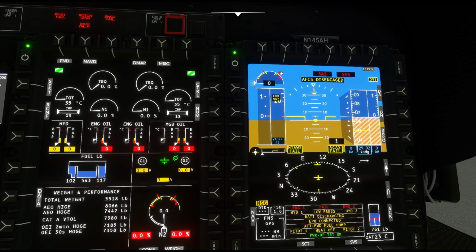95.4 is right about here where your low rotor light is going to come on. And right in here is where that high rotor is going to start screaming at you. So you're going to get some beep, beep, beeps. And then when you get here, it turns into a solid tone that cannot be acknowledged. You can't get rid of it. All right, so this is the absolute max the rotor is allowed to be.